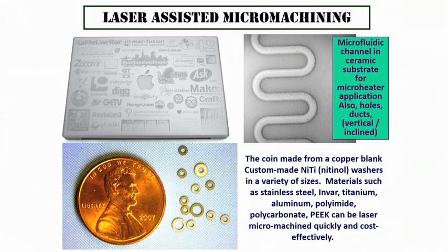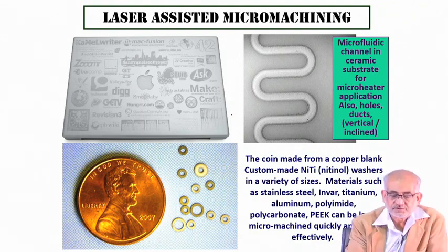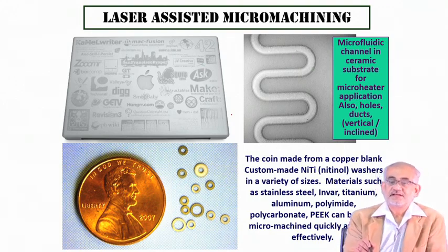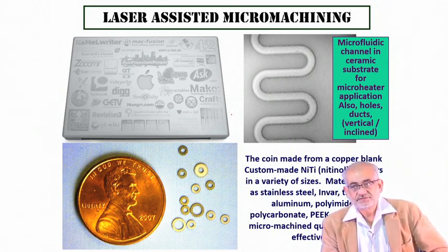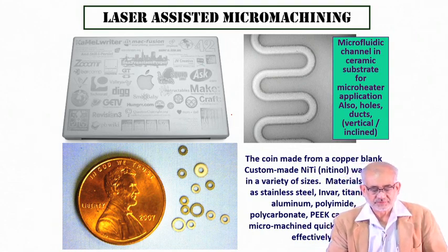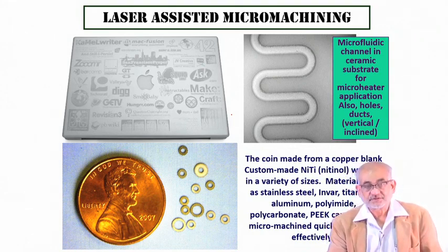So here is an example from a commercial house that you can create so many types of marking. You can literally create different markings and scribings on metallic surface. You can even bring in colors by way of controlled oxidation. So various forms of color tinting are possible by exposing a certain amount of gas and controlling the interaction time and power. The depth of the oxide layer that you create will determine the color on the surface. And of course, the basic composition of the substrate is important.